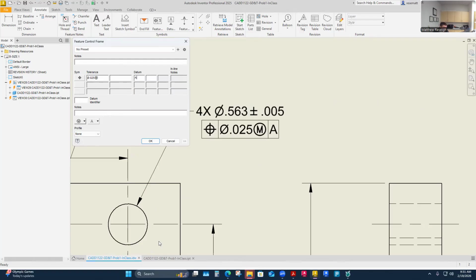So I think of this geometric control like this: datum A impacts that control, and datum B does too, at least as far as its axis of symmetry through the part, which I'm not explicitly controlling any more than just generally implying that I still need it to be perpendicular to datum B, which is the front surface that I'm really drilling into. And so adding B here, while there's no dimensions associated with it, I'm applying that I am still perpendicular to that datum as I bore this hole through.